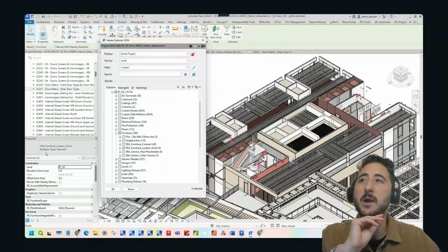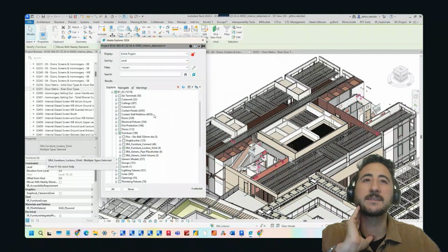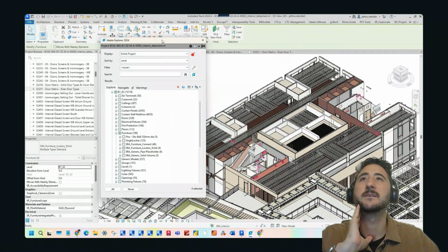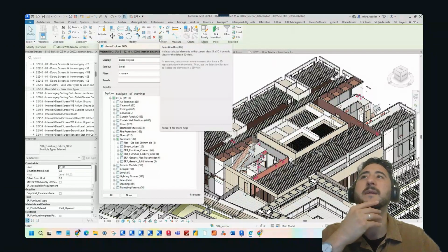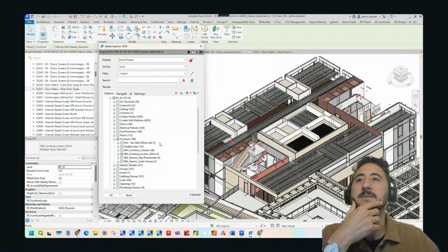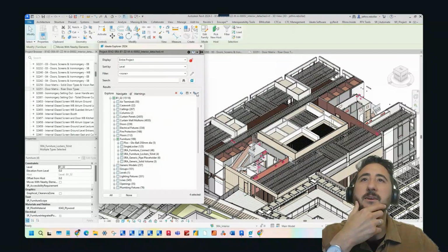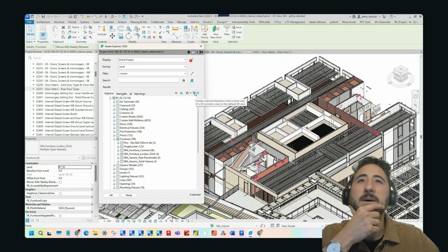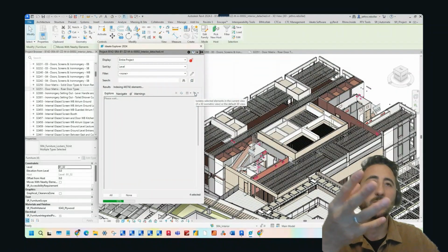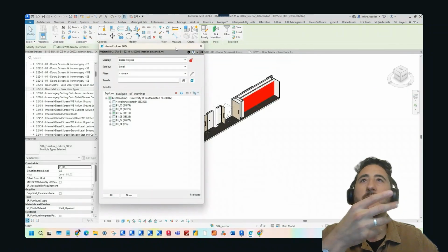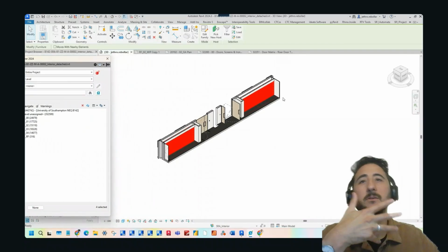as I can see within the properties window here. But I actually want to isolate them in the view, in my 3D view here. So if I go to this box looking thing, which is similar to the box within the view here, I think that's the Modify tab, sorry. So I have them selected here, and I could just go and isolate them within the model. And if a 3D view isn't what's up on the Revit at the moment, it'll create one.